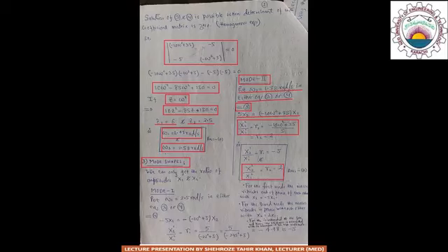or x22 upon x21 is equal to R2 is equal to 2, where x22 is the mode shape of the second mass at the second natural frequency, and x21 is the mode shape of the first mass at the second natural frequency, and their ratio is equal to 2 with the positive sign, which means these two mode shapes are in phase with each other.